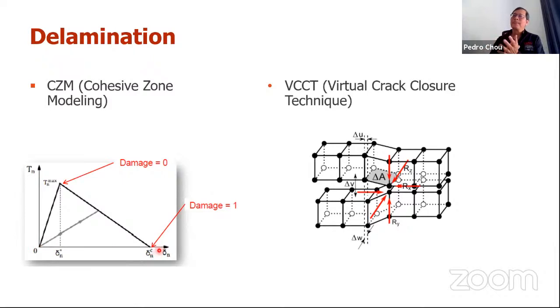So as the lamina starts opening, you can define a force deflection curve, where if the deflection is within a certain range, no damage is inflicted to the material, and when you unload it, it is still linear and comes back to its original position.